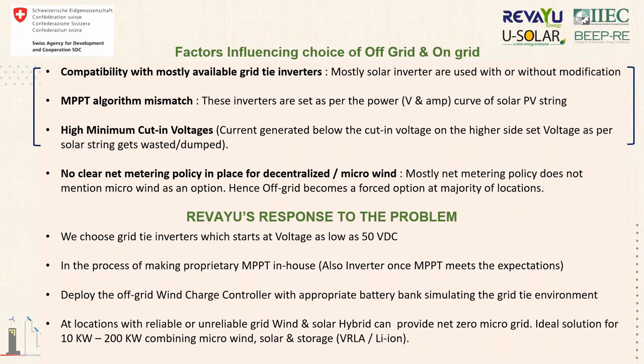So what we do is choose low voltage grid tie inverters and feed directly to the load. We don't export. We install at places where the power requirement is very high at any point of time, so whatever power we generate, there are no chances of losses or of it needing to be exported. We also choose relatively very low voltage grid tie inverters.